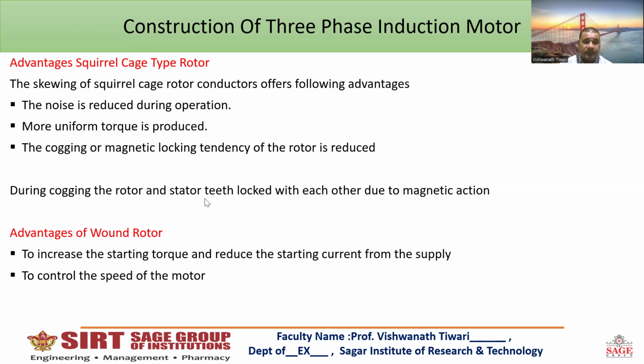The advantage of a wound rotor is to increase the starting torque and reduce the starting current from the supply, and to control the speed of the rotor.